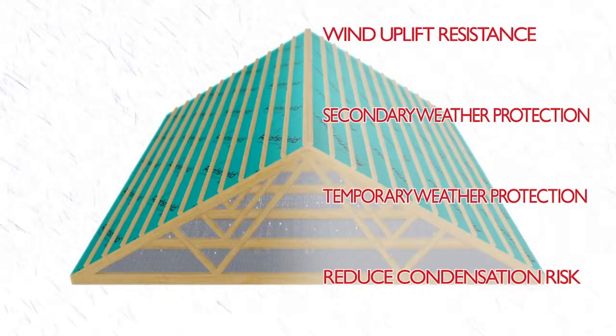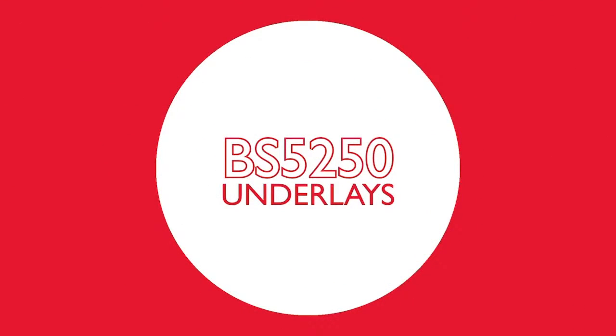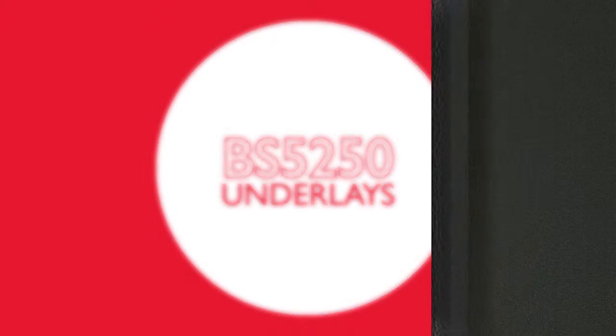How they do that varies depending on the characteristics of the underlay. BS5250 defines two primary types of roofing underlay and a third subtype. All these types are considered suitable for the role of secondary weather protection, so the main differentiation is in their characteristics regarding vapour and condensation.